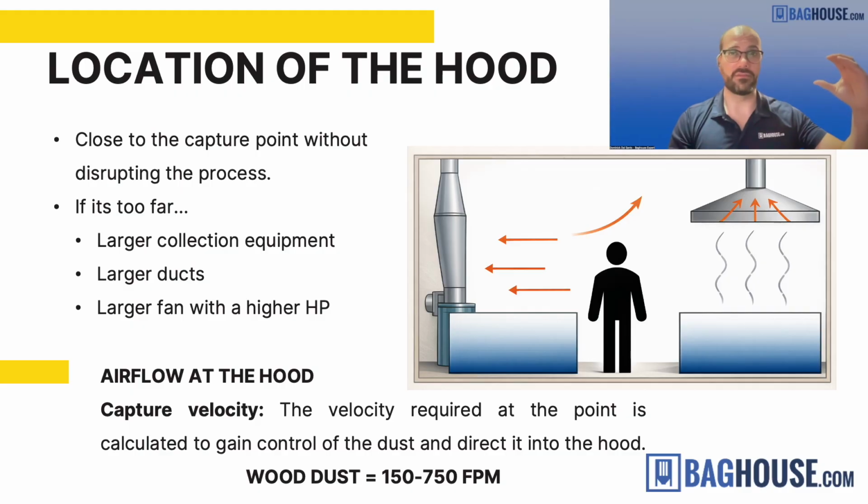Many times it's off to the side and the air is being pulled in sideways. So this could be something like where you have a grinding wheel or buffing wheel where the pickup is behind you or across from the worker. And that's because it's pulling sideways. It's easier to pull the dust into the duct sideways than it is trying to pull it up against gravity. But in any case, wherever the hood is designed or put, the idea is that it's capturing all of the dirty air and all the dust that's generated at each source.